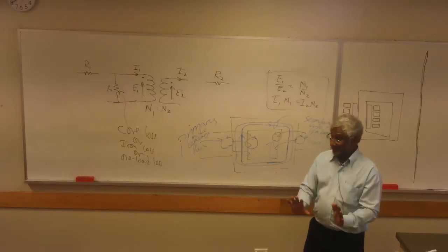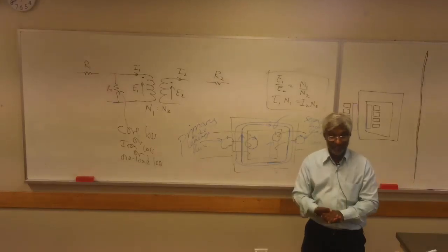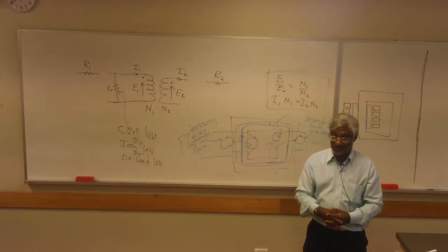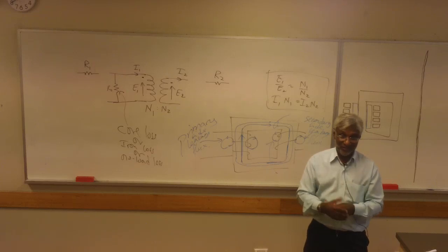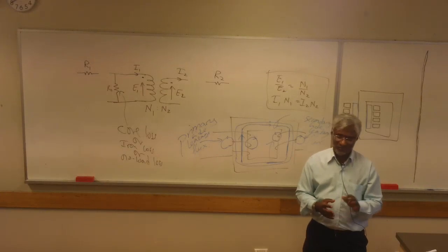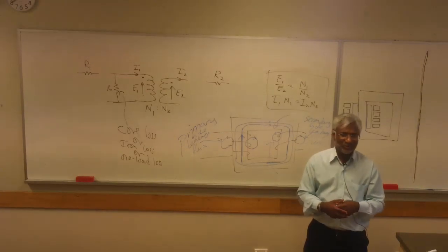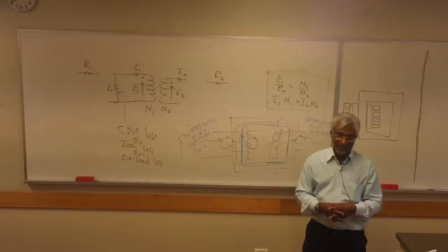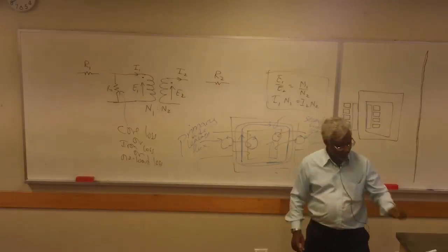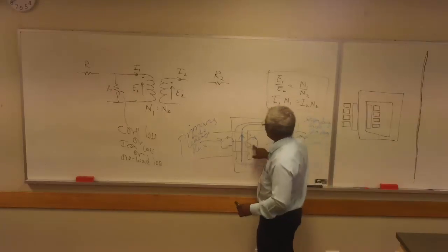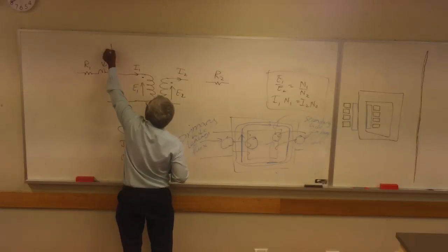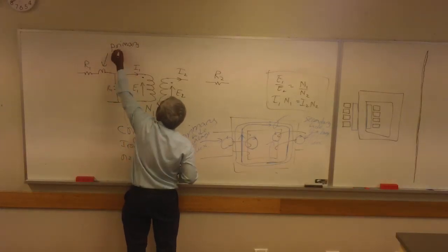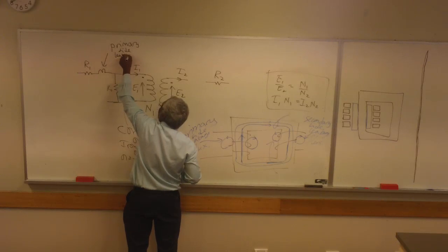I will put up a video that's dedicated to that, so you can watch that. But every time I say inductance, what should come to your mind is a bunch of flux created by a current. And the amount of flux per unit current is the inductance. As simple as that. You don't have to read 10 books on it. No point reading 10 books on it. So when people say inductance, you know exactly what it is. Okay. So there is an inductance associated with the leakage flux, and we put that inductance here, and we call it primary side leakage inductance.